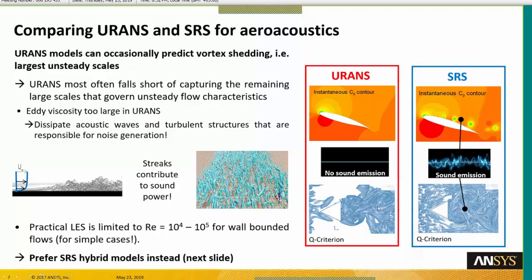And behind this, if you place a probe to capture some variation of acoustic pressure, for example, you can recover some creation of sound in an SRS calculation, but only if you have the proper mesh definition. So you need to be careful. If you don't have the proper mesh definition, you will miss all this acoustic information because you will damp it, as we saw previously.